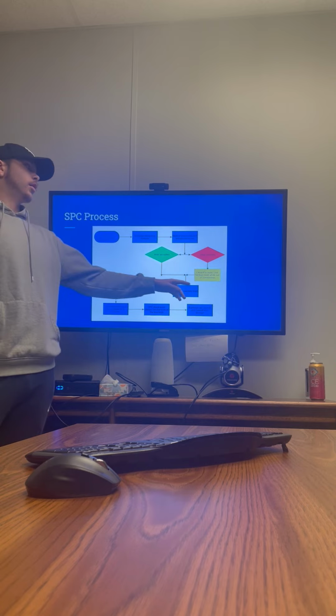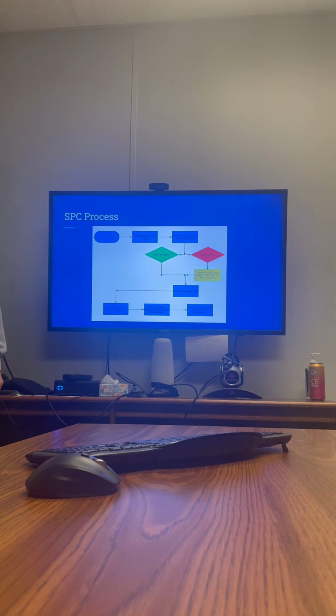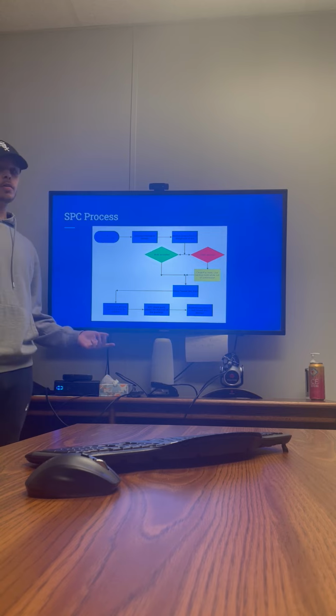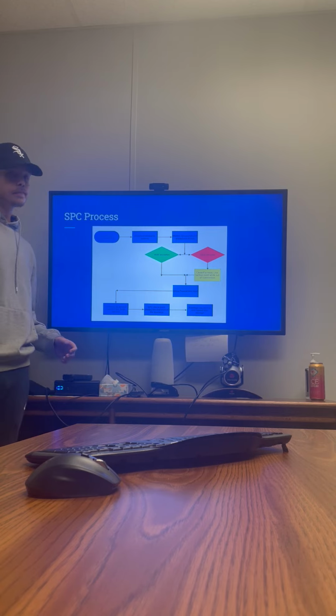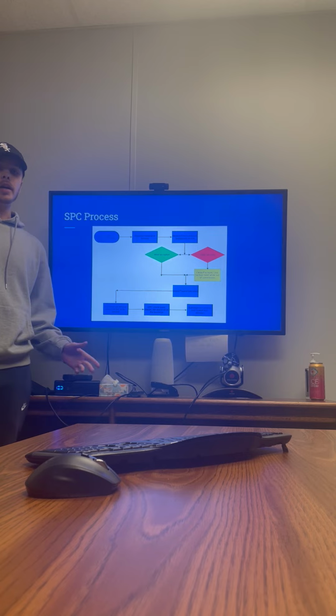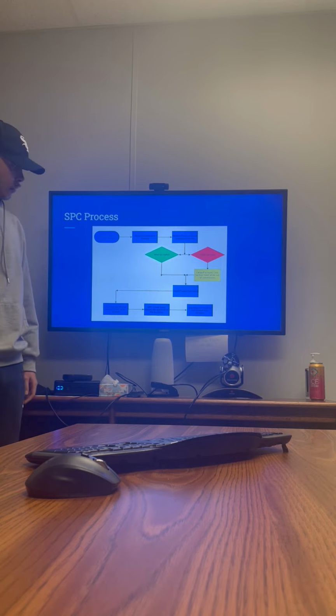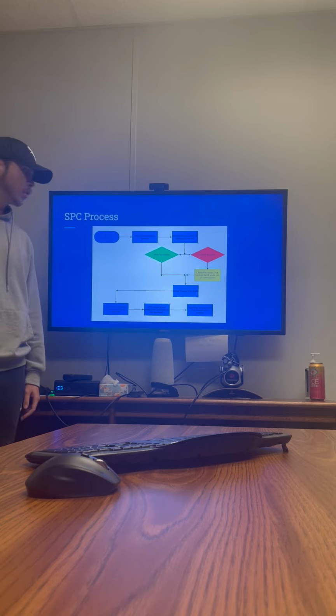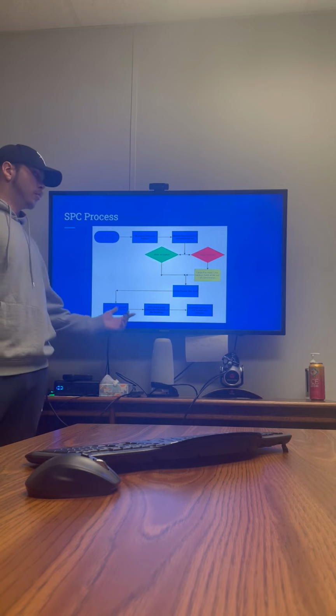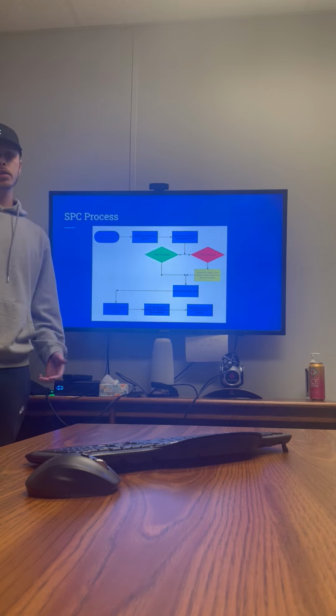And so after that, you go down to the metal being poured into the mold. The molten aluminum is poured into the mold and the bushing is created then. Once the bushings have been poured, they start to move down the line, which is where we are implementing our SPC checkpoint. Our SPC machine is going to go in and check the diameter of each bushing. From this, we will be able to tell which bushings are within and without the control limits. And then after the checkpoint, they're moved to storage, or if they need to go straight to somewhere else, they are transported.